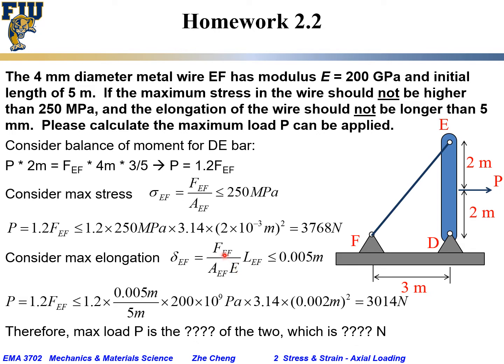And what is stress? Force over area. Stress divided by E gives a strain, times L gives us the absolute change in length.